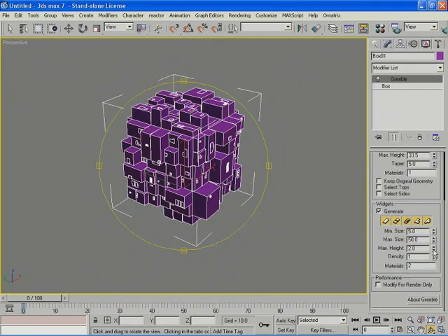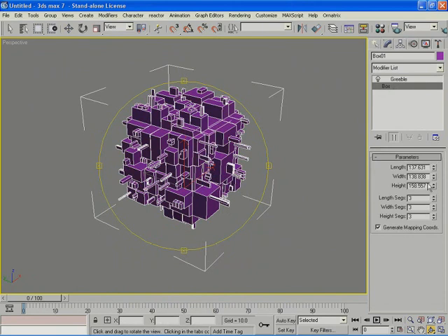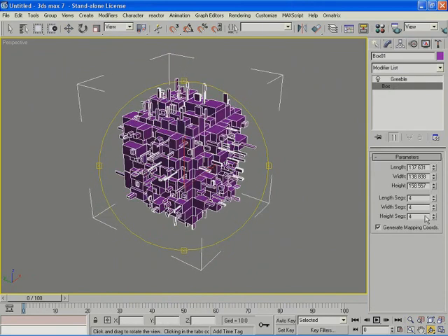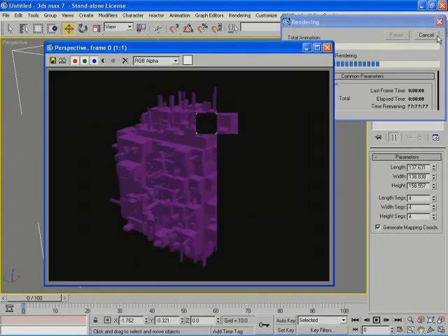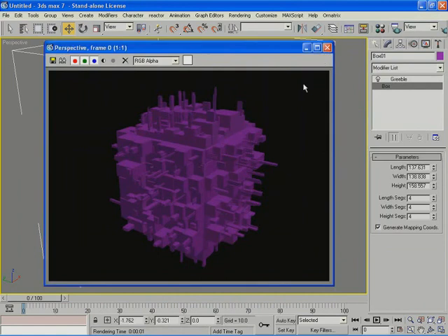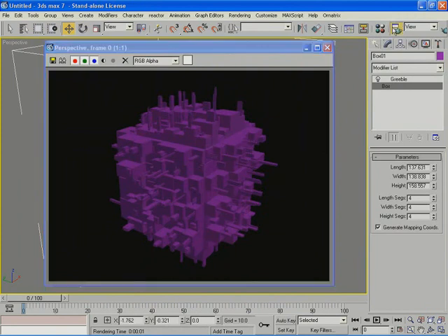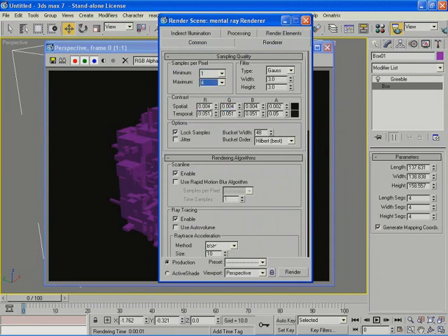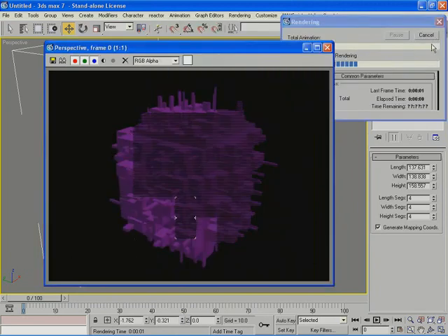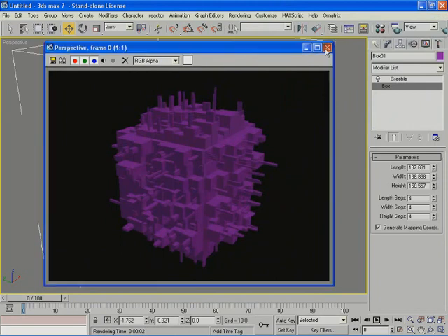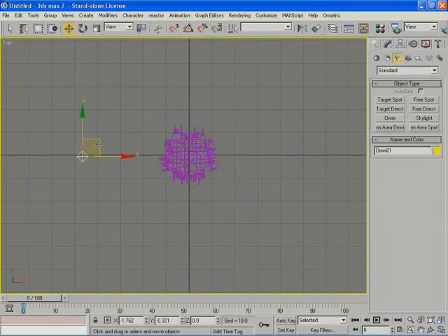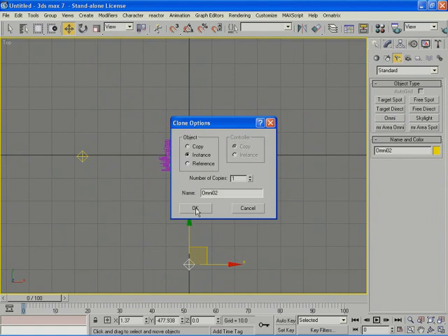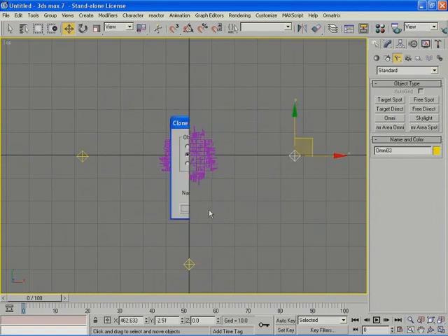If I render with my regular material, I'm going to get no contrast between the objects. Now, the low detail, the pixelation that I'm getting is from the low sampling that I chose. So let's go to 1/4 so that we get something a bit better. Okay, I'm going to add a few lights around just to see the actual detail. But the lighting here is of no relevance, because what I'm working on is a material that will generate the occlusion. And I repeat that, the occlusion is the soft shadowing that you get whenever two surfaces are close to each other. So let's decrease the multiplier here and render.